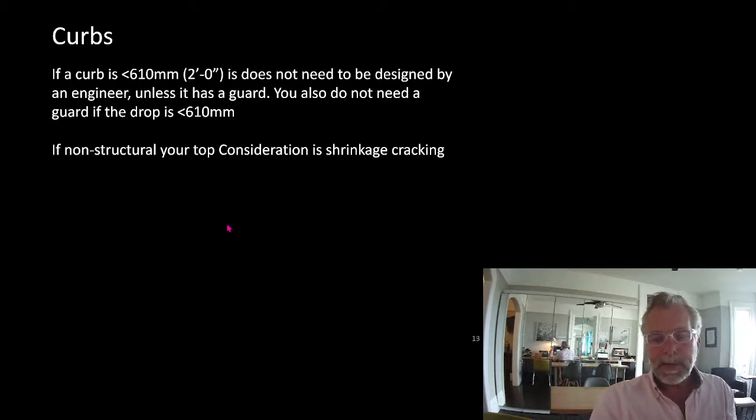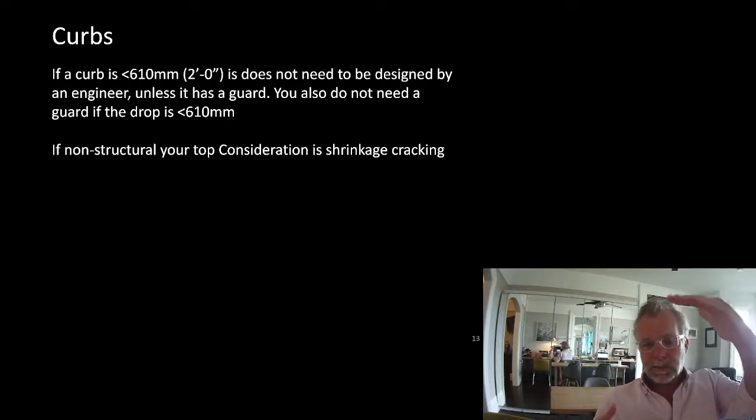You also don't need a guard on top of a curb necessarily. Guards are required in the building code where there's more than 2 feet, or more than 610 millimeters, of elevation differential. You would need a guard.